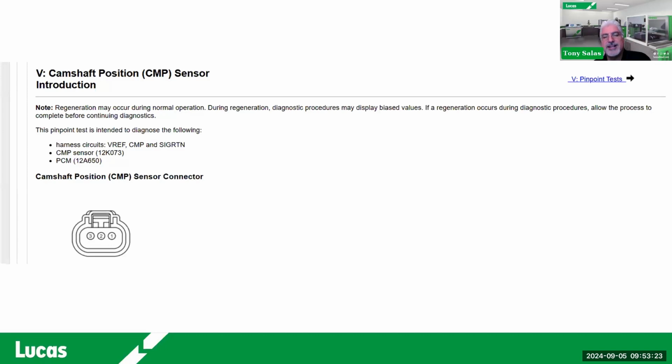an RPM signal. So like I said, you're going to look at your RPM signal. Now I know that on the 6.0 and 6.4 you can look at your sync signal as well, or your FICM sync. But what about when you don't have that? In this case, you can look to see if it's present. Now Duramax will tell you if the signal is present, but once again, it won't tell you how good it is. Now you're going to find out sensors can use 12 volt, 10 volt, or 5 volt reference voltage. Yeah, there is that across the board on all these different light duty diesels.